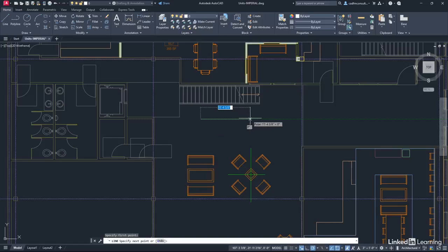I'm going to drag across to the right. My polar tracking is on, remember. It should still be on from the previous video. And you'll notice now, can you see I've got an option there in the blue highlighting to type in an imperial measurement. So you have to type in, so I want 8 feet, and then I put what is known as an apostrophe, like so. Then I spacebar, like so. And can you see it's done an 8 feet line, 8 foot long line. Now, I might have wanted to put some inches in there. How do I put inches in?